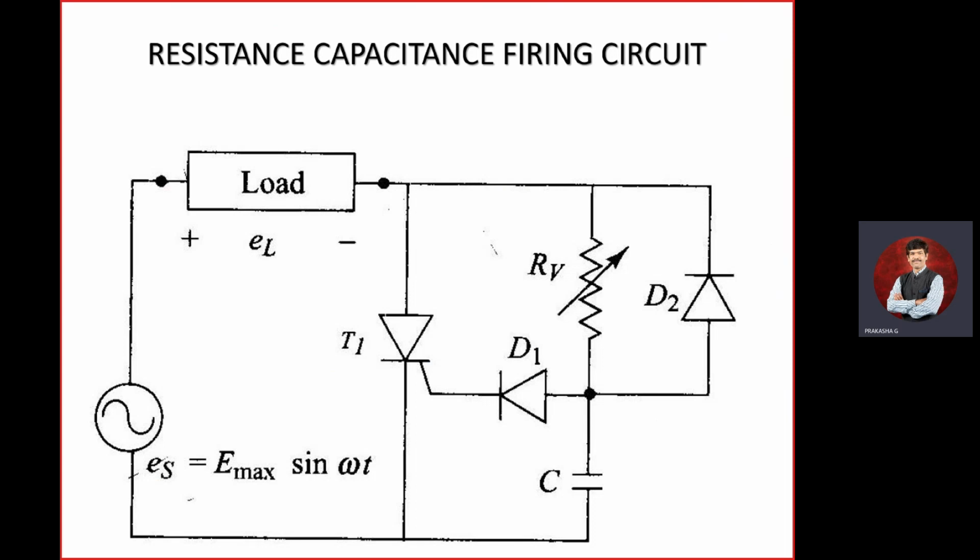The capacitor is used for charging and discharging. There is a positive plate and a negative plate in the capacitor. If it is very small in size, there are no polarities. If the capacitance is bigger, that is microfarads, we will have polarities, positive and negative. The same thing applies here.